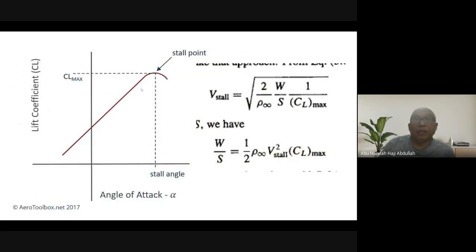After stall, here is an example of the engineering: the angle of attack and lift coefficient. The maximum lift coefficient will be at the top of this peak, and also the stall angle. So the more you increase the angle, the more lift you get, but at one point you reach a place where it will be saturated, or where it will be the maximum. If you increase the angle of attack further, you may have flow separation. That's why we have to understand this curve from the tests that have been done by the scientists, as well as the angle of attack minimum or maximum you can use.